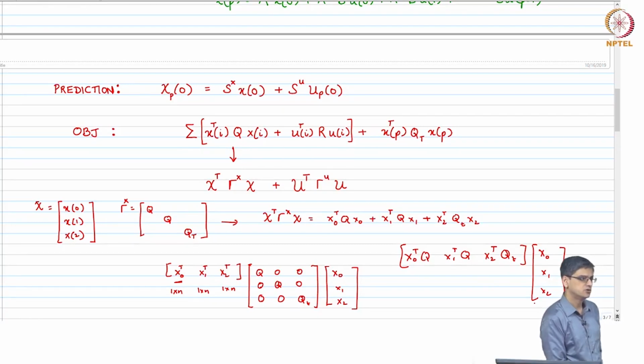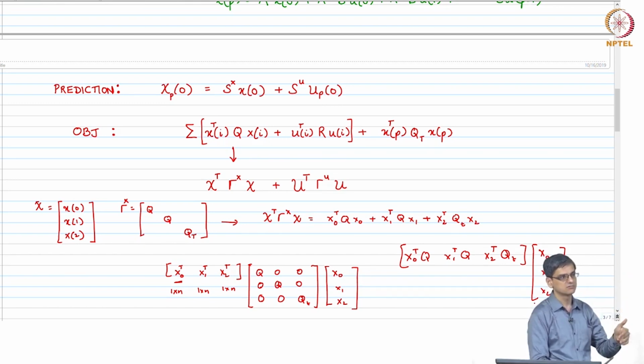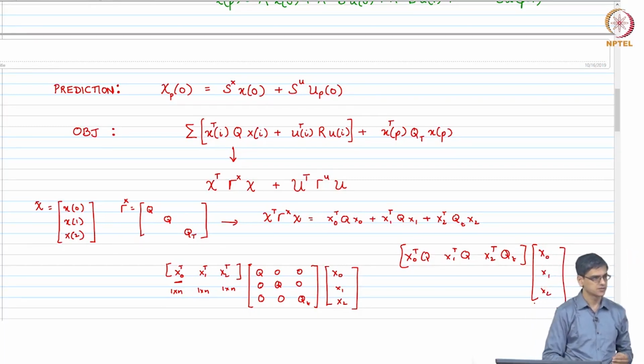Next module, or maybe next module, we will talk about how to handle disturbance rejection and how to handle set point tracking, okay. Easy way to handle it, you augment your state. So, your state Z will be X R or Z will be X D R, where X is the state, D is disturbance, R is set point, okay. We'll come to that.